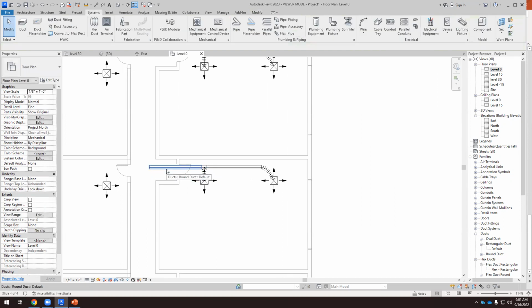Again, the fewer ducts, the better. So having the main duct going across a classroom, I wouldn't do it. That's why we have hallways. So we make sure that we move this out, and then the main duct is here. So all these diffusers or all these branches are connected to the main duct.